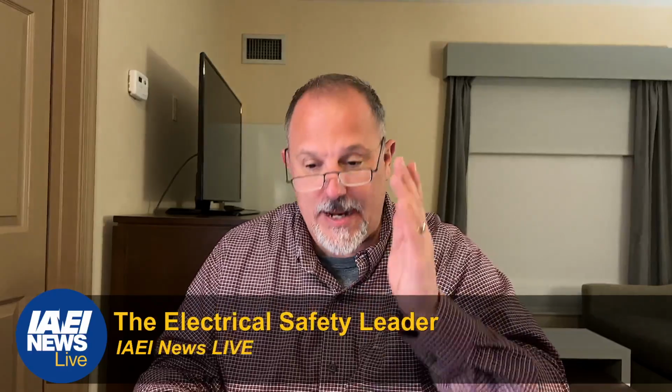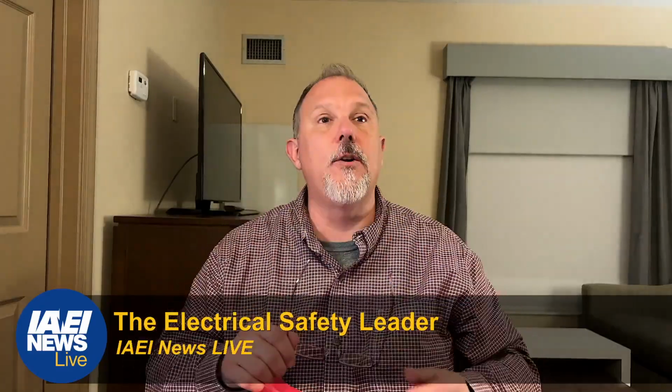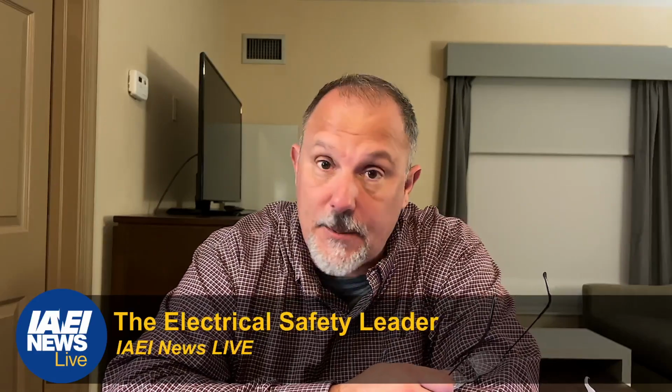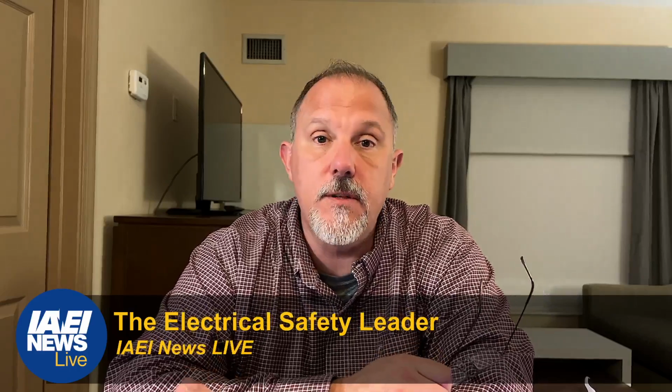All right, so that's basically 210.8. We're worried about shock protection. We're worried about being able to identify when current goes outside of the normal path. The expansion that we see in 210.8 is driven by Consumer Product Safety Commission requirements. And what else? We added some clarity. We expanded some of the exceptions. We removed some duplicate data and information references.